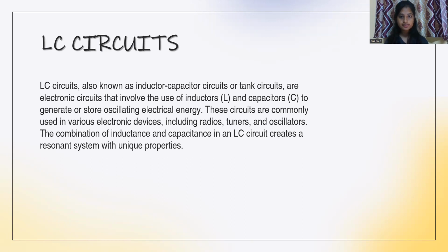They are also called tank circuits. They are electronic circuits that involve the use of inductors and capacitors to generate or store oscillating electrical energy. These circuits are commonly used in various electronic devices like radios, tuners, and oscillators. We can use the inductor and capacitor separately, but their combined effect gives us unique properties, that is, a resonant system. That's the reason we are combining them.